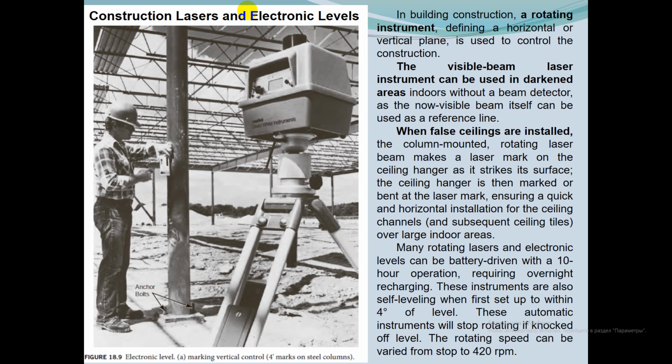In large indoor areas, many rotating lasers and electronic levels can be battery driven with 10-hour operation, requiring overnight recharging. These instruments are also self-leveling when first set up to within 4 degrees of level.